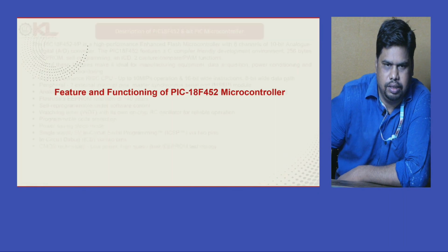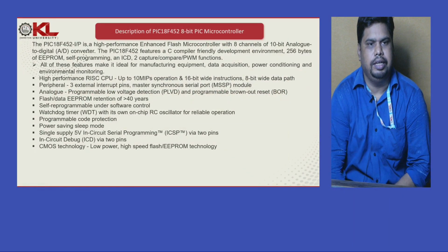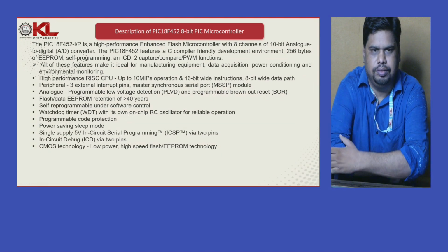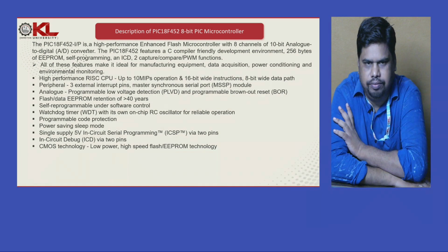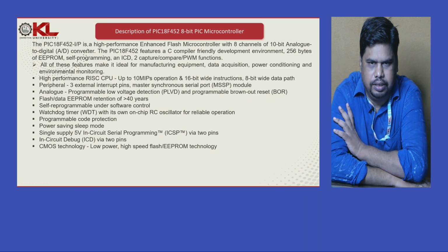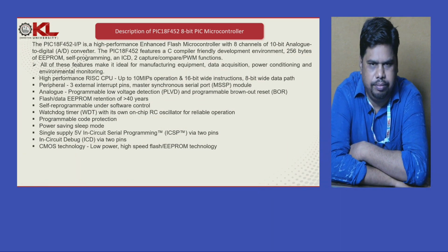To the next slide, what are actually the features of this PIC 18F452 microcontroller. So you know that it's an 8-bit processor with 8 channels of 10-bit analog to digital converter. PIC 18F452 features a C compiler friendly development environment, 256 bytes of EEPROM, self programming, ICD 2 and CCP module. All this terminology I will be discussing in the coming slides.